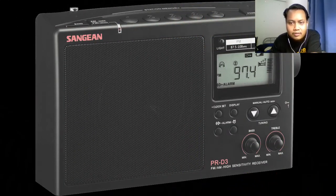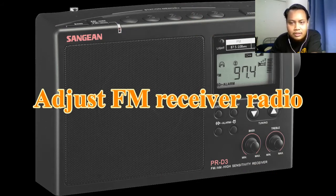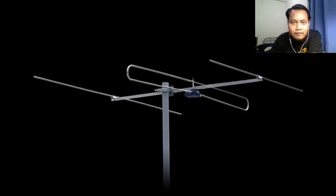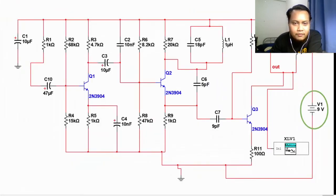And since there is no visual output to recognize the exact frequency at which the transmitter is working, you will need to adjust your FM receiver radio within the range of the frequency mentioned to get the frequency at which the transmitter is transmitting. After modulating the audio signal with the carrier frequency, the signal is then sent out through the antenna, which is the output. All of this connection is in DC, connected with 9V battery.